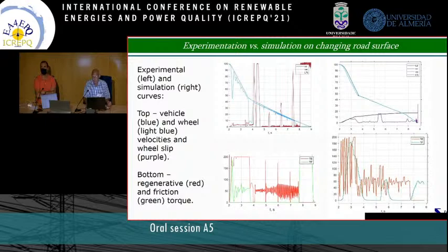Here we demonstrate two situations. First, asphalt, next, icy road. Sometimes they change, and the system must understand that the situation has changed. This is why the torque changes, the slip changes, and our control changes.